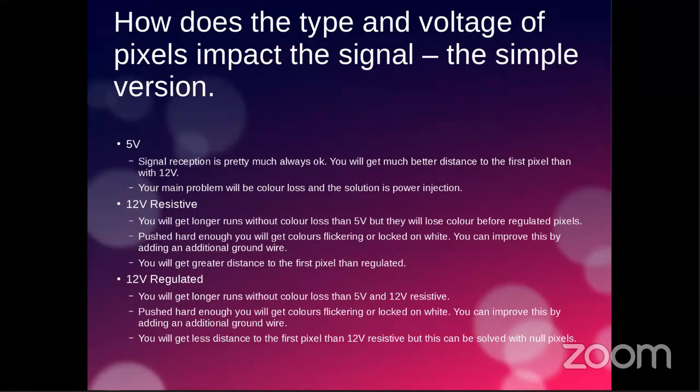I run 5 volts easily at the end of 60-foot cables, and I've never had a signaling issue where the 5-volt signal was not being received. Your bigger problem will be color loss, and the only solution to that is clearly power injection. But you can run your signal as far as you like.